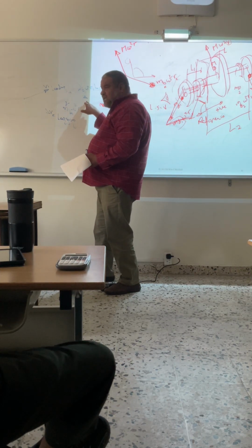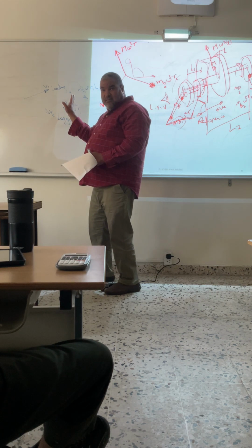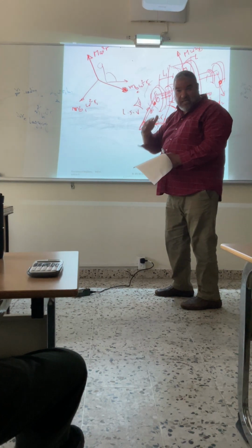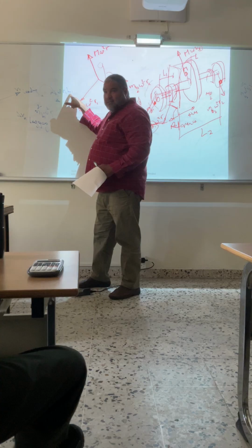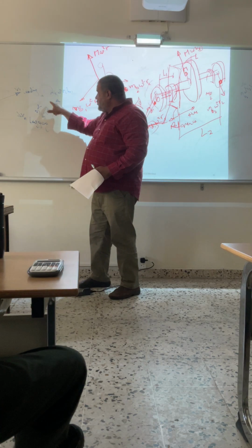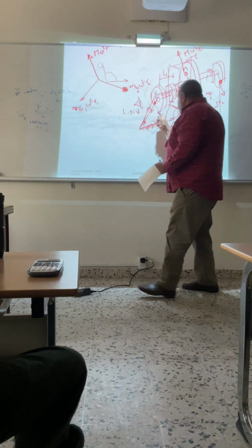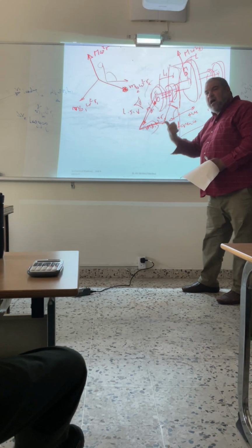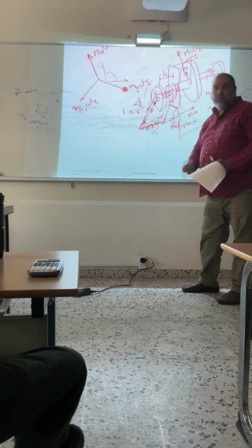And if you go to the other case, your moment is acting in this direction, right? I'm speaking here about MB1, guys, the balancing masses, which is on the negative side. So now you are saying MB1 omega square R1 L1. So what is the conclusion that I can come up with? As long as the distance or the arm of the force is negative, then I should end up having what? Leading or lagging? Leading moment.